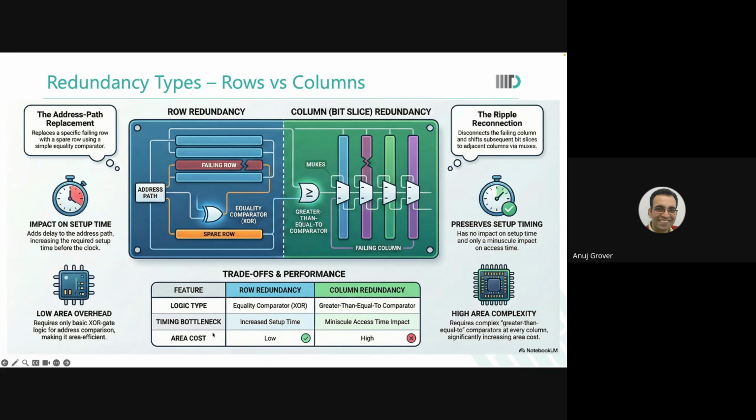So look at which new cells and which new designs I can acquire or adapt from existing solutions. In a new technology, you know that you have to design everything new. But because again the time cycle is limited, you have to lay out everything and do the schematics for everything. So you might not go to a new design architecture or lots of innovation in the circuits in the first compiler in your new technology. In the first compiler in the new technology, you will probably only copy paste the architecture or design style of the previous technology, whichever was best in the previous technology. You copy paste that and ship it out. Again, secure and fast.